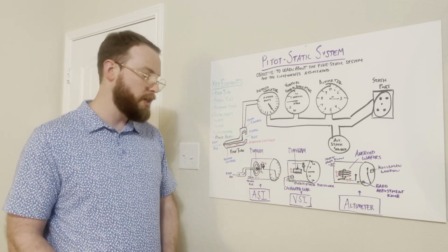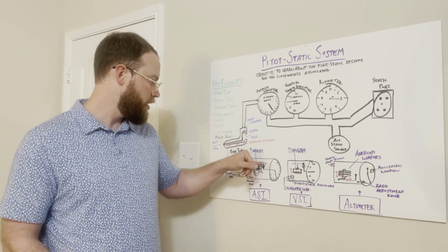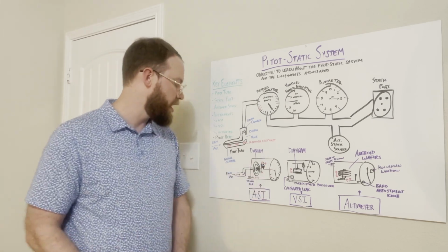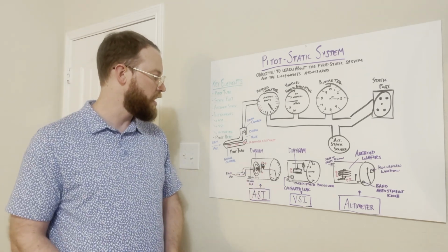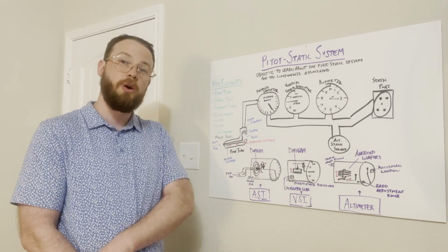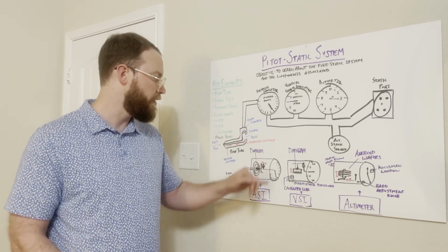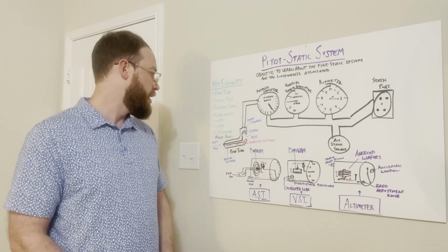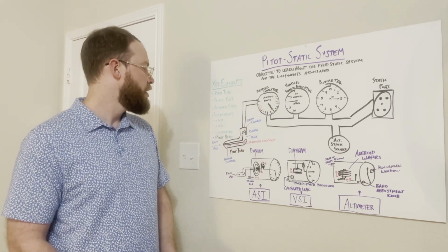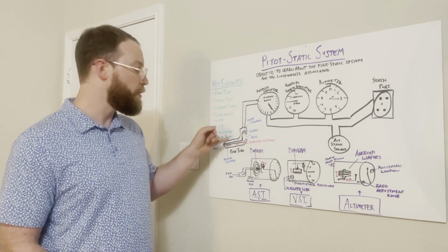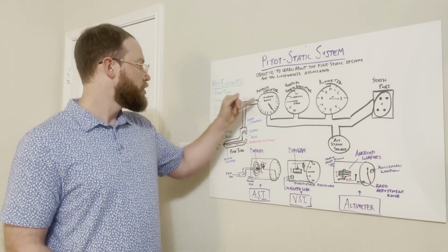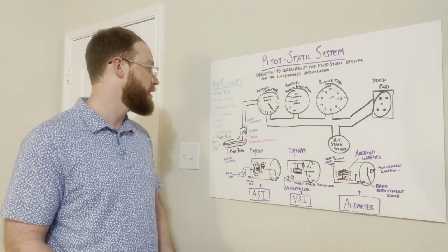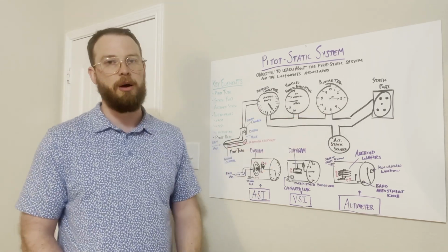It moves these mechanical linkages here, as I wrote here with the little red arrows. It's going to spin the needles, and then on the inside lead toward the outside face and show the indications of that here on the face of the instrument. So that's kind of our airspeed indicator. Now that's directly related to information that we get from the pitot tube. So the pitot tube and the airspeed indicator are our best friends. They work really well together, but we also get information from our static port.